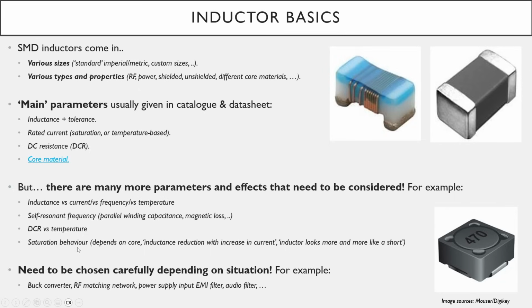But saturation is something we typically want to avoid in most applications. Saturation, you can think of it as, as we get to saturation, the inductor looks more and more like a short. I'll leave some links in the description box below which go over saturation in a bit more detail. As you can see, there are many more parameters to inductors than just the inductance and maybe current rating on its own. And these parameters need to be considered and chosen carefully depending on the situation.